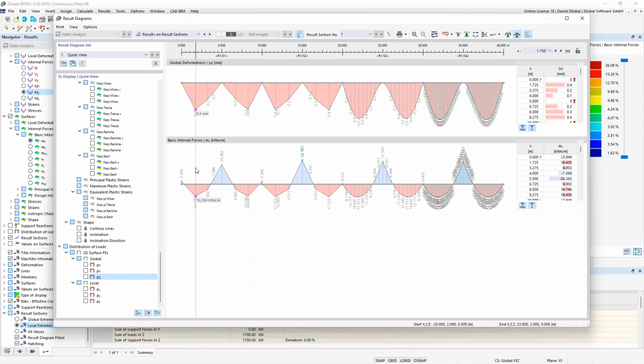And you see also here between these FE nodes, the results are also not good, because we underestimate here a complete distribution of nodes. So when I take a closer look to the middle of one span, and this is in this case 2.5, for example, we see here that we have a value of 11.67. The same when I do this for the next surface.